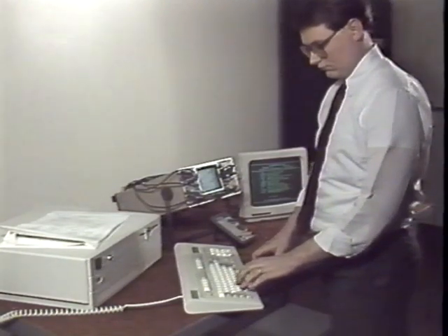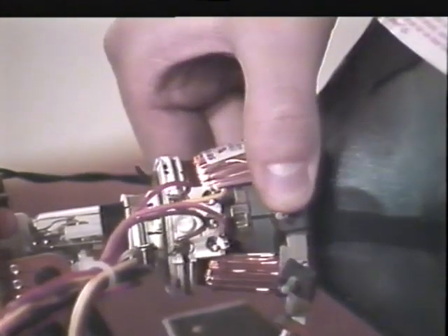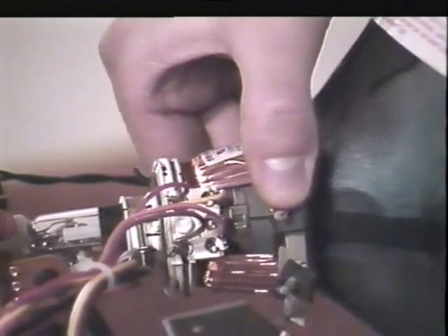However, there are still a few mechanical alignments that we must do. The first of these is the raster tilt adjustment, which makes sure that the display area is perpendicular to the face of the screen. To make this adjustment, first select a crosshatch pattern. Loosen the screw that holds the yoke to the neck of the CRT and rotate the yoke around the neck until the picture is straight up and down. This process orients the yoke so that the magnetic fields that it produces drive the beam directly across or down the screen. Be careful not to touch the yoke wires during this process.